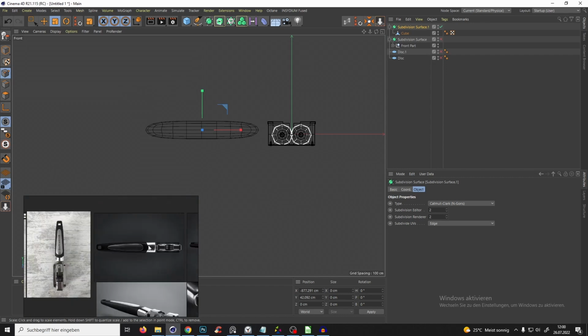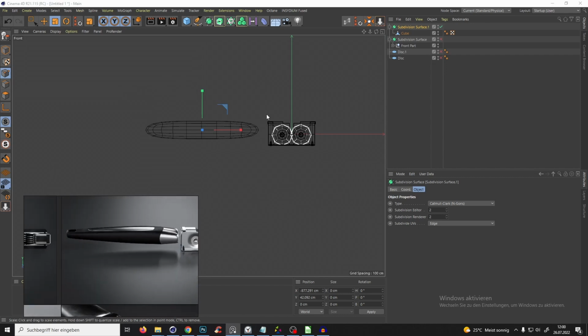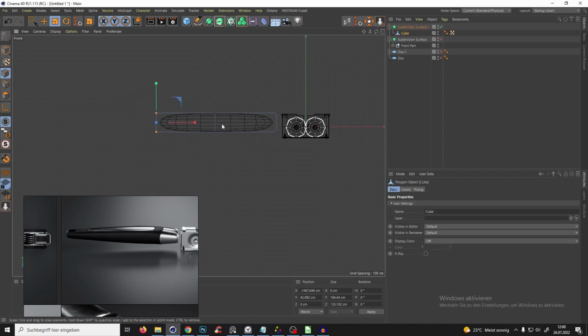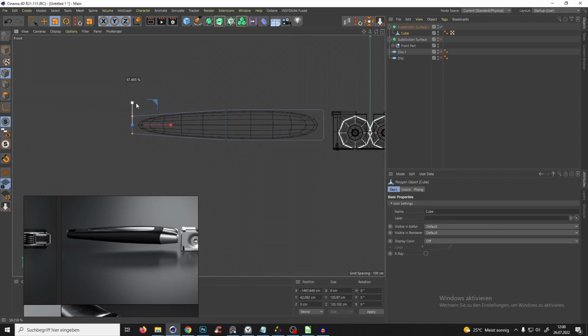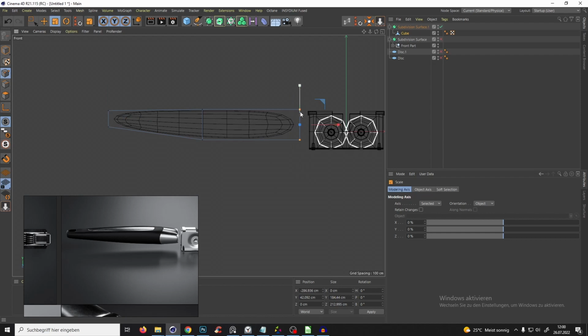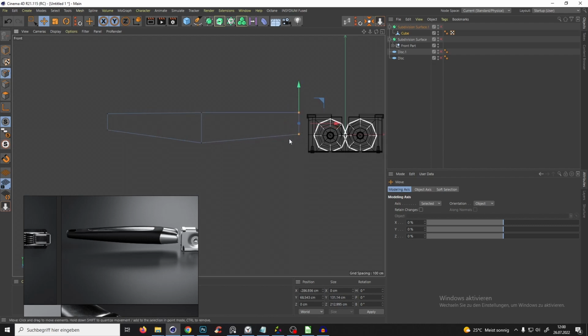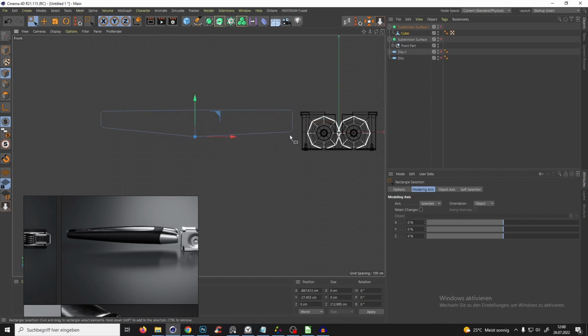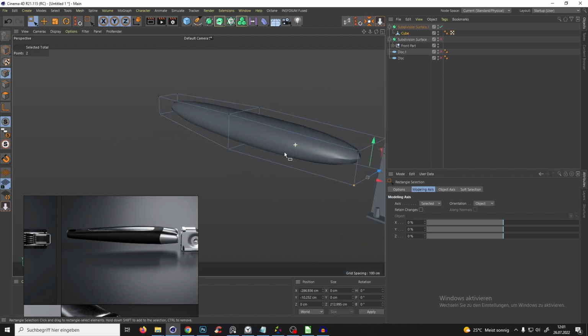And then we go to our front view, and if we check the original one, if we go to our cube here, you can see that those 2 points have definitely to be smaller, and we can bring them a little bit up. And the same goes for here. We select those points too, and with T for scale, we just scale them a little bit, something like that. Let me see. Maybe bring those 2 points a little bit up, and maybe those a little bit. Yeah, so you see, it's kind of the shape that we want. Yeah, that's enough for now. So yeah, something like that.